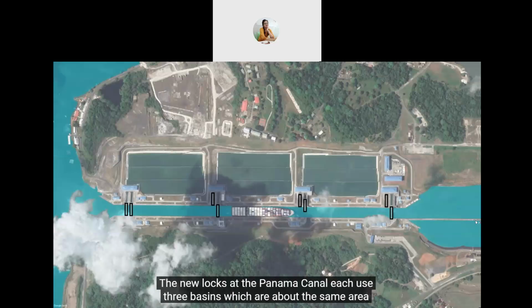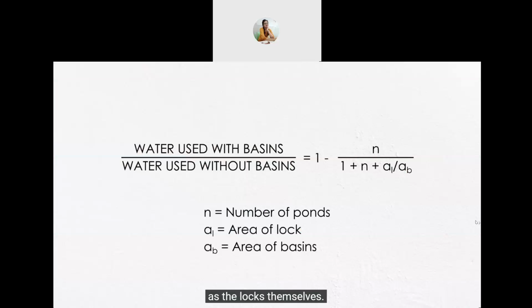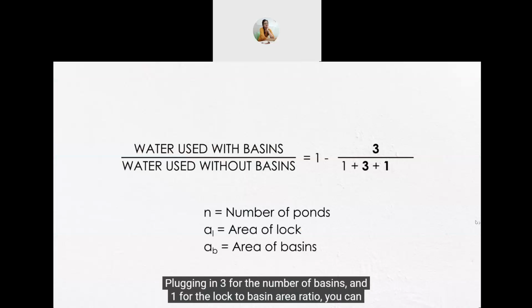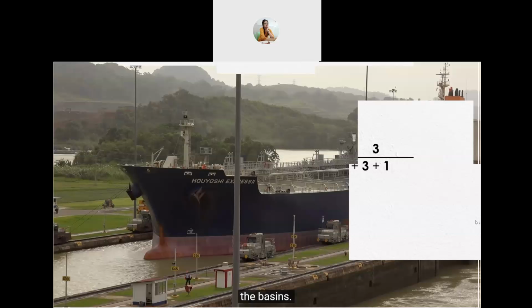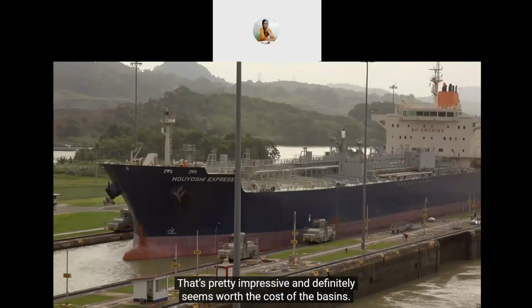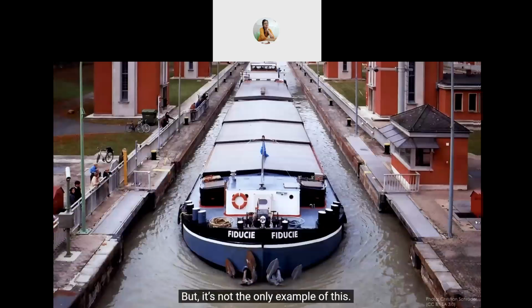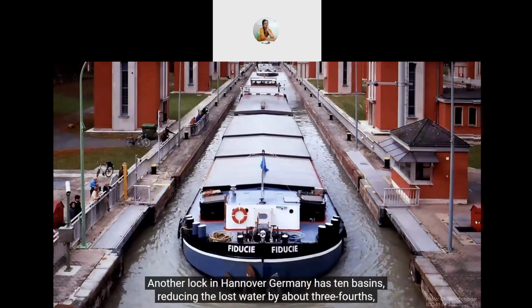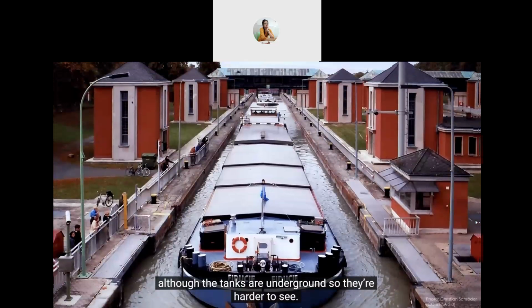The new locks at the Panama Canal each use 3 basins, which are about the same area as the locks themselves. Plugging in 3 for the number of basins and 1 for the lock-to-basin area ratio, you can see that the new locks use only 40% of the water that would be required to operate without the basins. That's pretty impressive and definitely seems worth the cost of the basins. But it's not the only example of this. Another lock in Hanover, Germany has 10 basins, reducing the lost water by about 3/4, although the tanks are underground so they're harder to see.